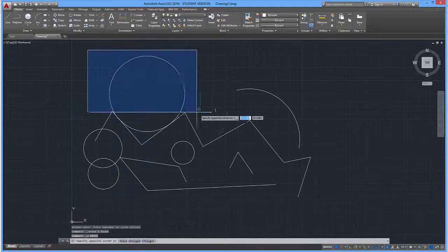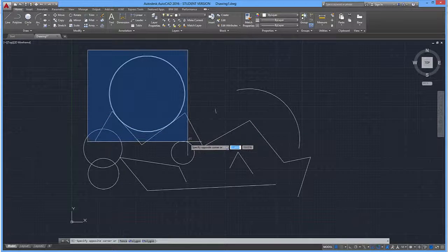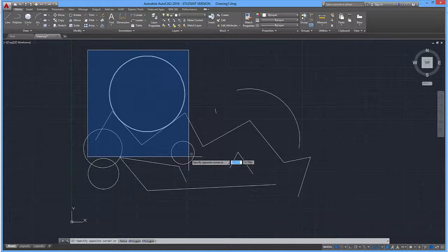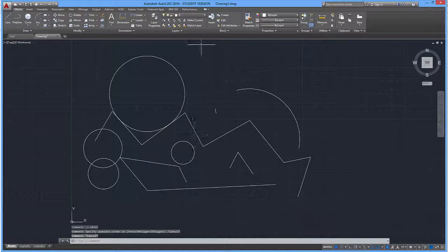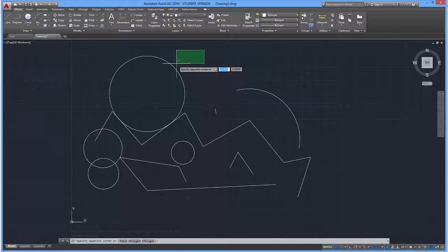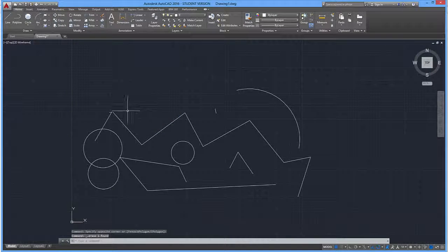But it also depicts different things. Moving from right to left, you have to select the entire object, like this circle over here, in order to delete it. So with the whole thing selected, but not anything else, I can delete that. This was a polyline over here, so I'd have to select the whole thing to delete that. Whereas if I move, right to left, sorry, this is right to left, then I can select that, and I can delete that. So you just have to touch a point, and it will delete itself.